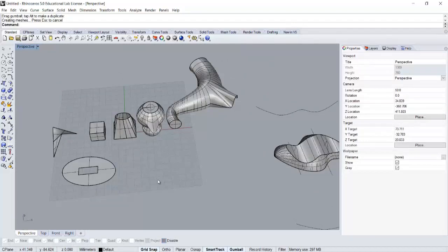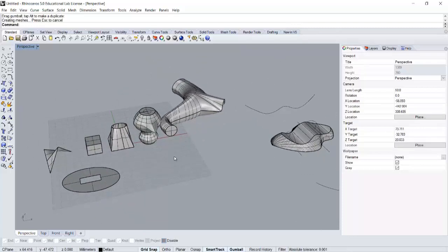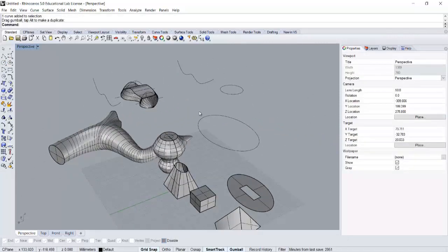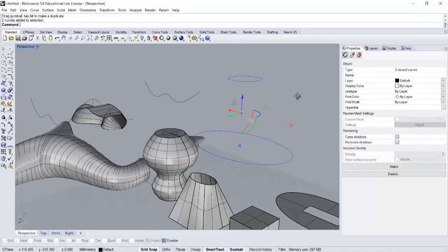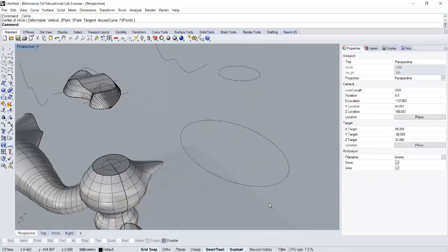One of the things that works really well with Rhino, but it takes a little bit of methodical thinking, is using the history tool, record history. Okay, so how this would work is, say I'll just do a simple one like a loft. Now before I go to the loft tool, I'm going to record history.